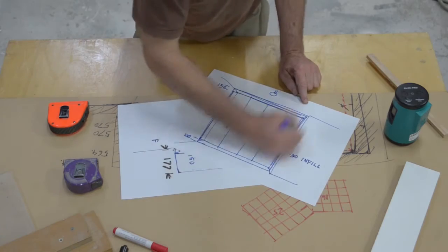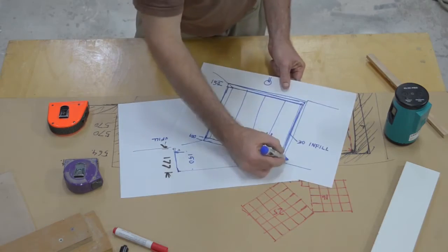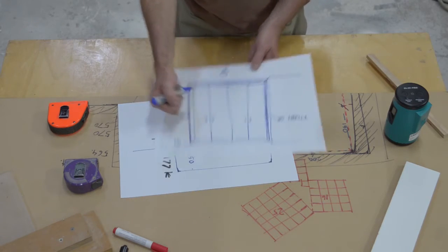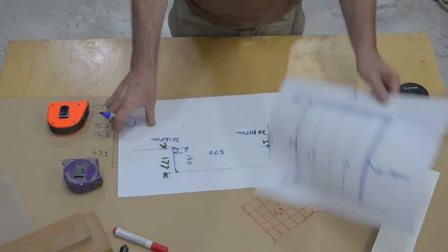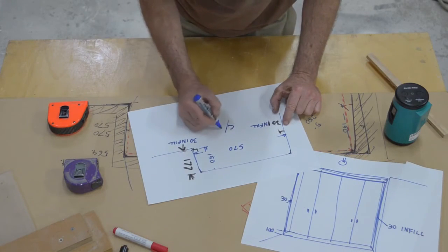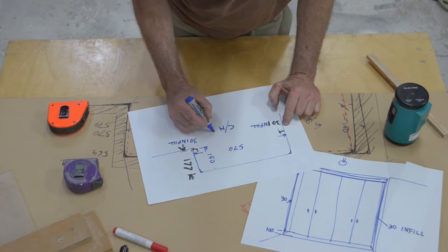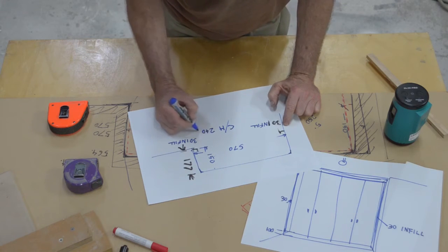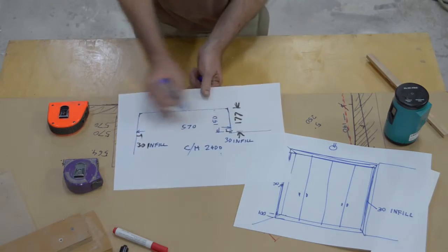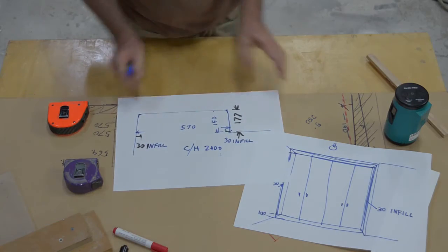And the height, I might mark the dimensions this way on the drawing, depending on what I needed to do. But if I've got the information here, that's fine. And what I would tend to do is put like the ceiling height, 2400 or whatever the height would be. And I might also measure the height in a few places. Depends what I see on the site.